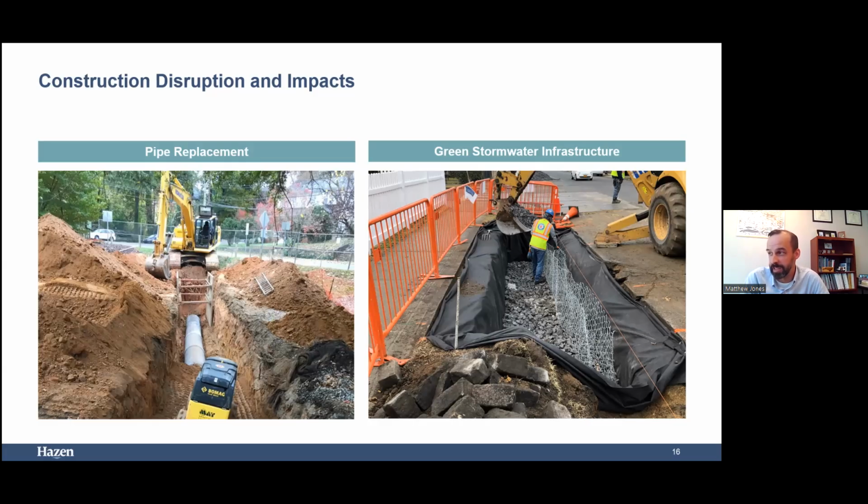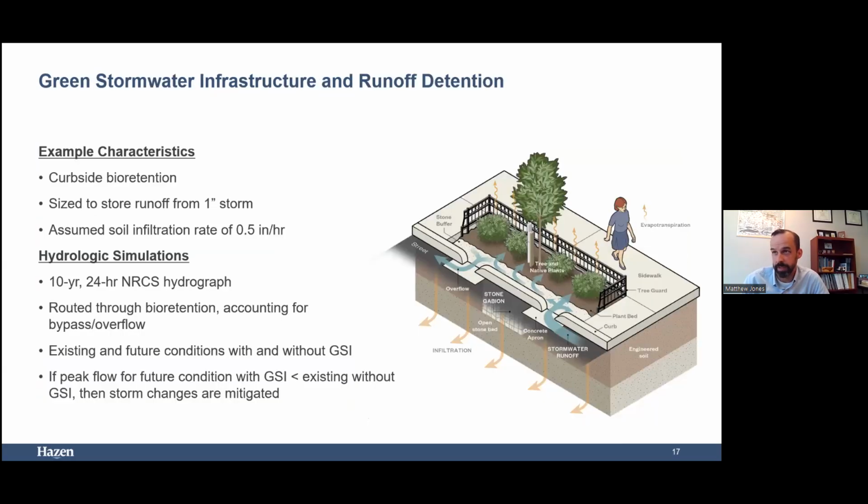What we wanted to understand is if green infrastructure could play some role there and provide a lot of benefit. Green infrastructure in this context, we're not expecting it to replace the role of piped conveyance infrastructure, but could it provide some added capacity such that upsizing could be delayed, or by managing some of the runoff from increased storm depths and intensities, could we negate the need to do that pipe upsizing? That was really the fundamental question that we were asking.